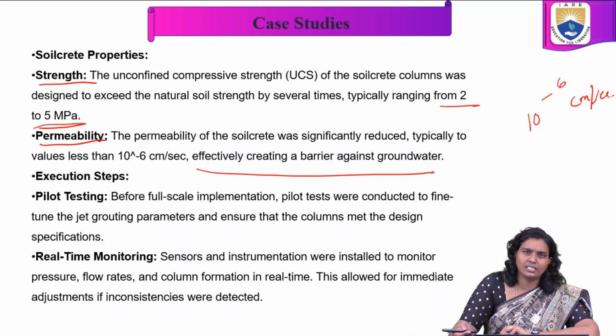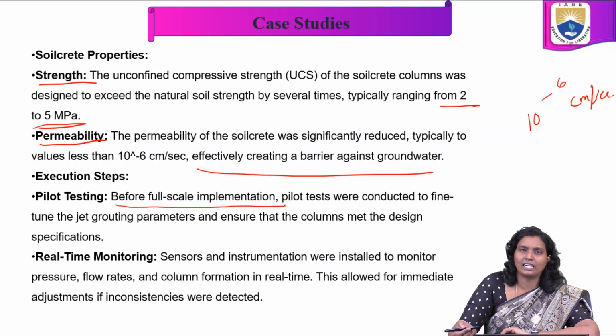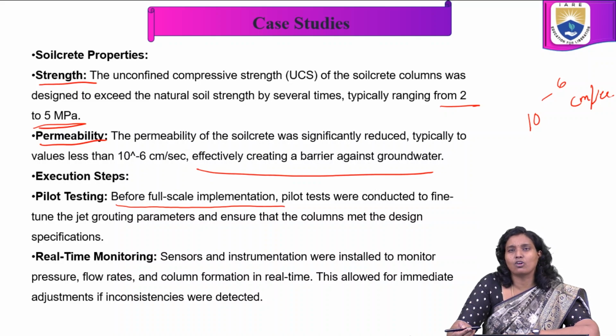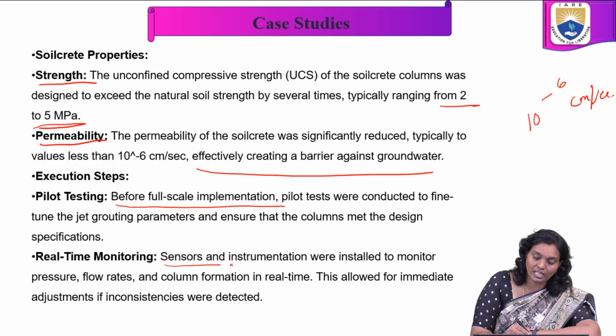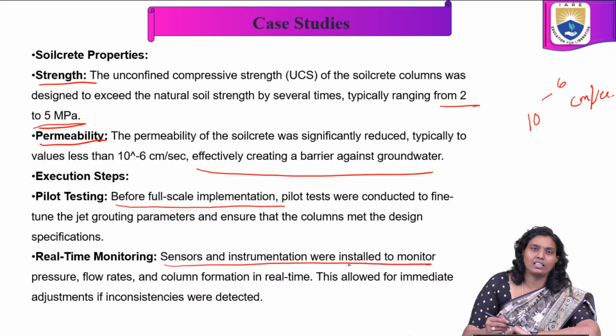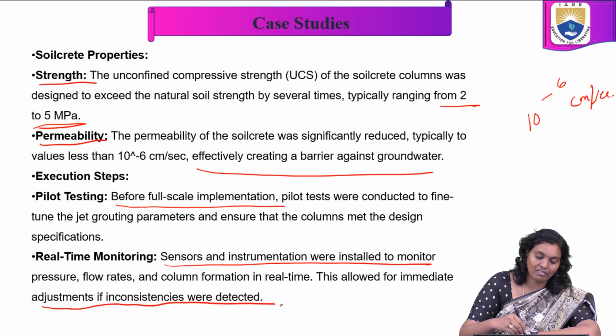In execution steps, pilot testing before full-scale implementation: a pilot test was conducted to fine-tune the jet grouting parameters and ensure that the columns met the design specifications. In real-time monitoring, sensors and instrumentation were installed to monitor the pressure, flow rates and column formation in real time. This allowed for immediate adjustments if inconsistencies were detected.